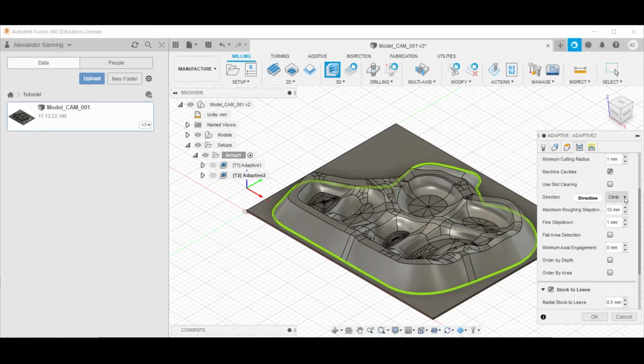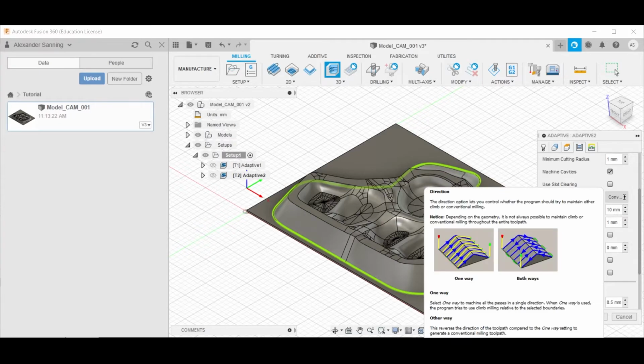Here we change the direction of the milling from climb to conventional, and this is because we're using a 10 mm in diameter tool, and thus it is more susceptible to deflection than the 16 mm tool, and thus it is a prudent thing to be on the cautious side and have it be milled conventionally, so as to reduce the amount of deflections. Deflection can lead to micro vibrations, and micro vibrations can lead to the tool getting loose from the collet, and that is something we want to avoid.